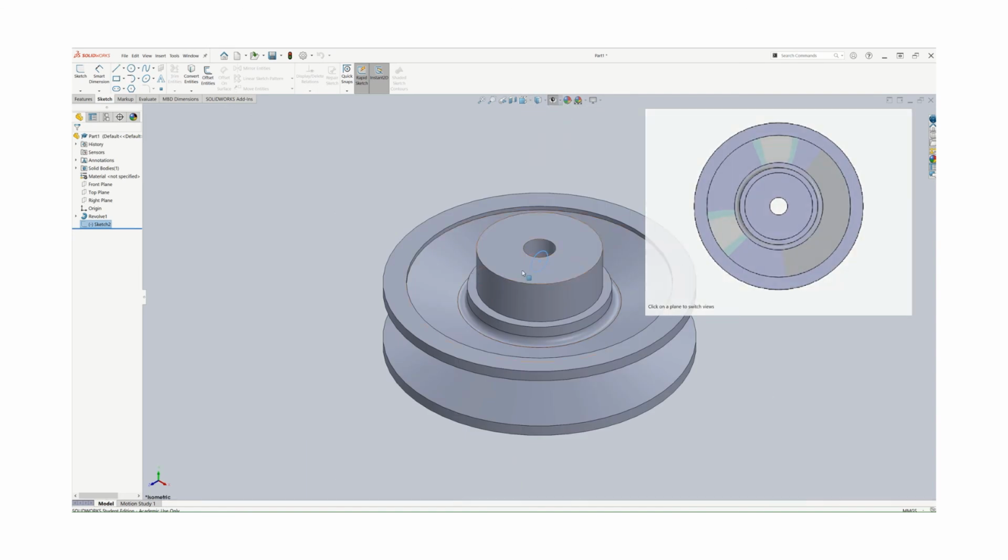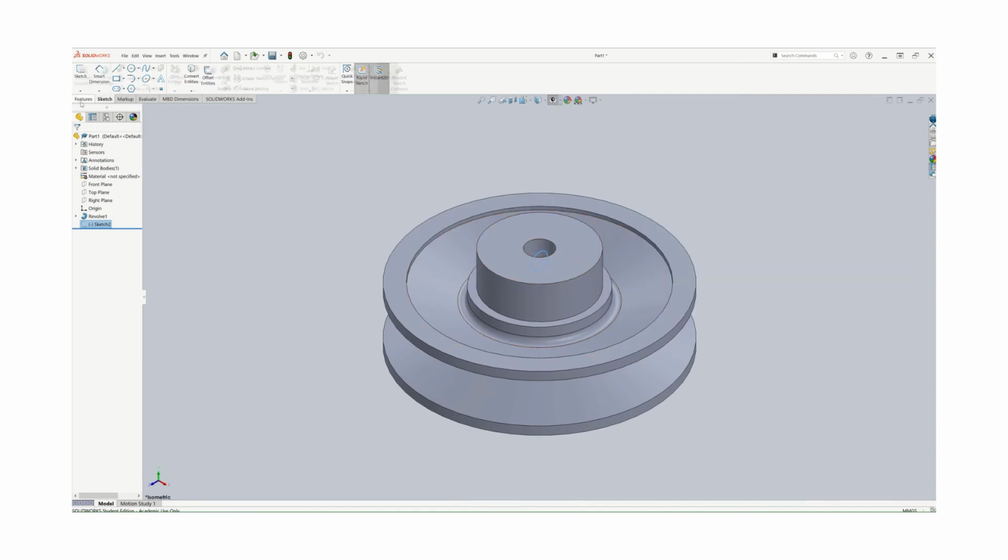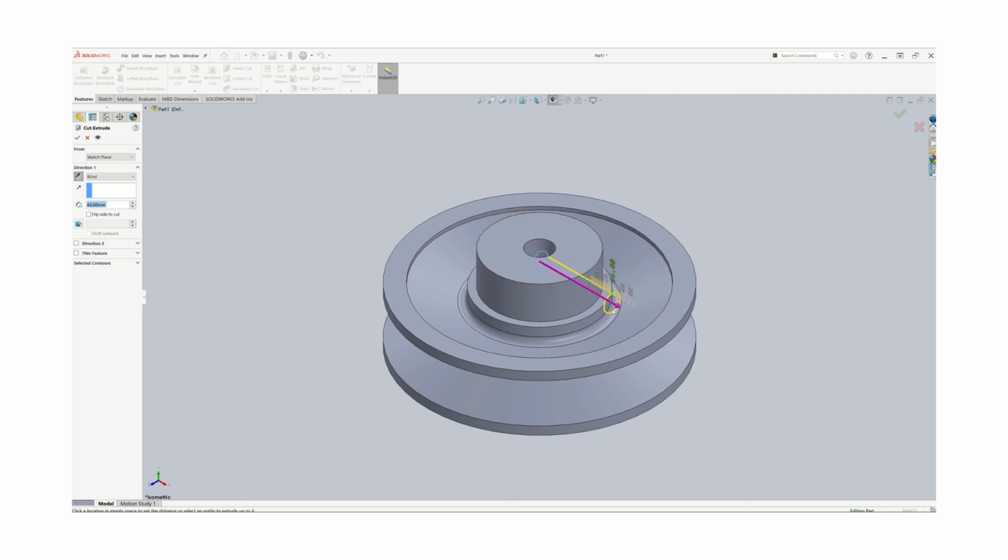In this case, when I try to cut, I will choose what is highlighted, the extrude cut, and then I could go that way, or I could change the direction here and go all the way through the surface, and then I will have this object. So this probably helps you to create some of those 2D profiles by using many offset lines and so on.